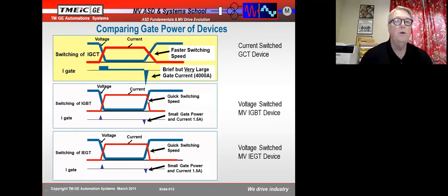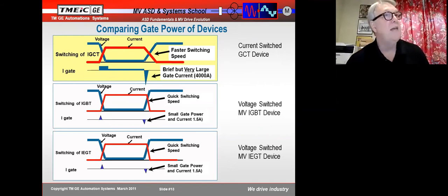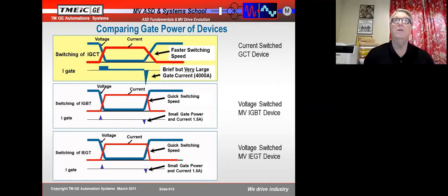And when you think about this, if you have a device like a transistor that's half on, that means that 50% of the voltage is going to be dropped across that transistor, and 50% of the voltage is going to go to the load. And therefore, you take 50% of the voltage times the current, and that represents the losses in that transistor. In other words, huge.